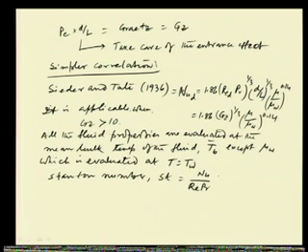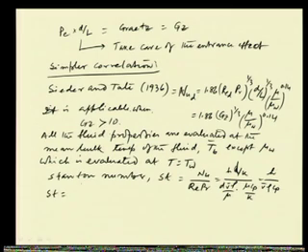If we put in all the values of Nusselt, Reynolds and Prandtl, we see it is hL by k, in this case it is D, hD by k into D V bar rho by mu into mu Cp by k. So, it becomes h by V bar rho Cp. Again, if we rewrite, h delta T by V bar rho Cp delta T.